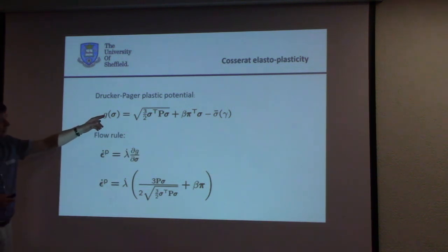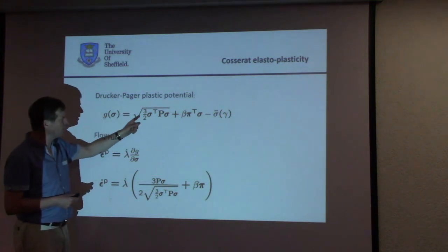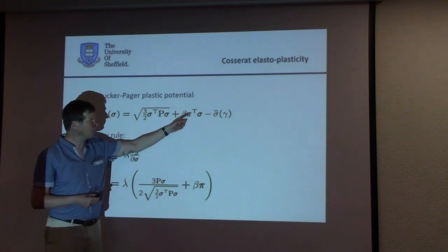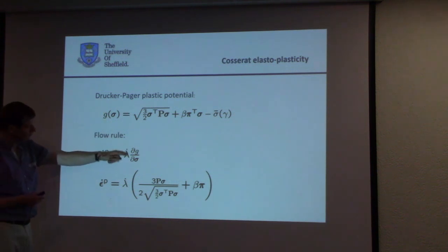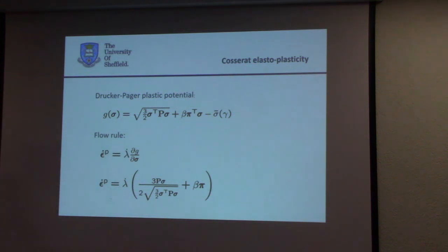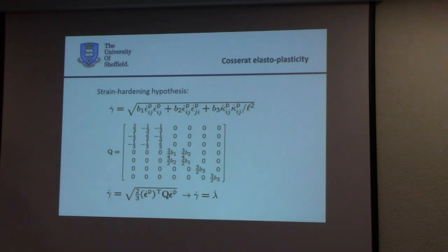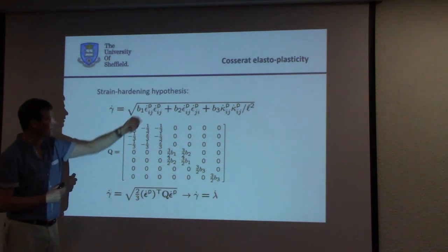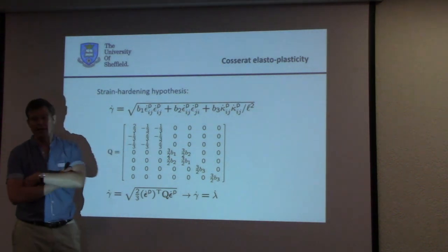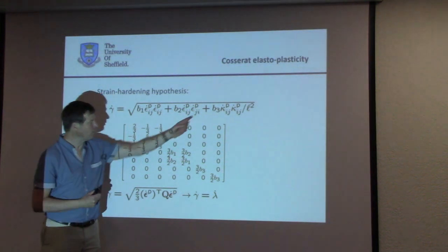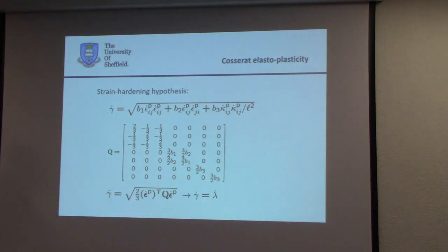So we have typically a plastic potential that's very much similar to the yield function, but with a dilatancy factor rather than a friction factor. So if we substitute this in here, we can get this by simple differentiation. And again, we have to define a different expression for our hardening parameter. Normally, we have just 2/3 times this, or 1/3 times this, plus another third times this, which doesn't matter because epsilon ij is symmetric. But now we have also to add the plastic microcurvature rates.